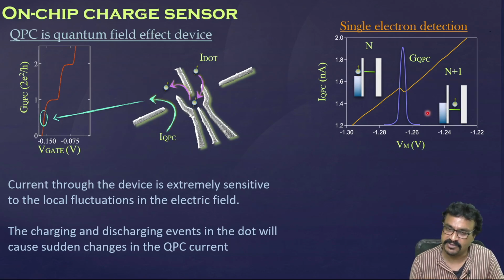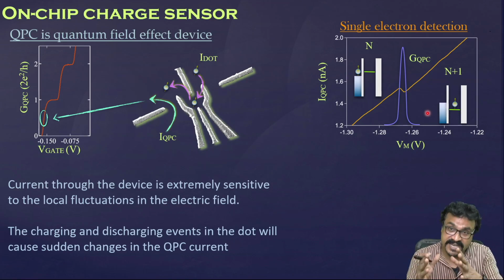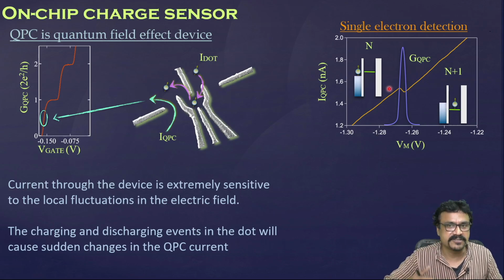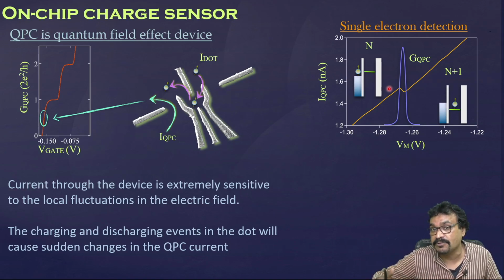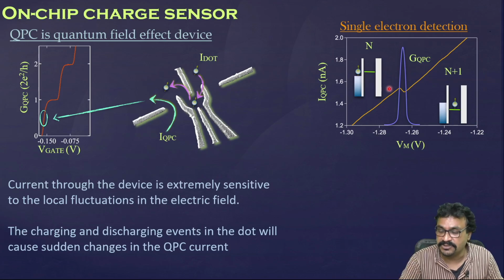As you reach the few-electron regime, in parallel with the transport characterization, you also check whether you see these blips in sequence. What you would see is that the Coulomb blockade oscillations stop beyond a certain voltage, because the barriers become so opaque you cannot measure the current. But you will see that these blips, or the derivative of those blips, peaks or dips depending on how you take the derivative, keep coming at regular intervals, and that is used as a sensor to see whether the dot is empty or not.